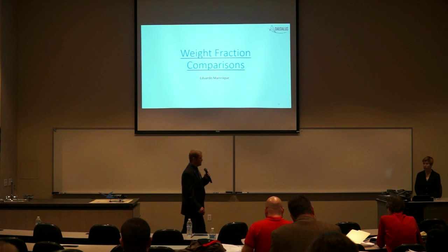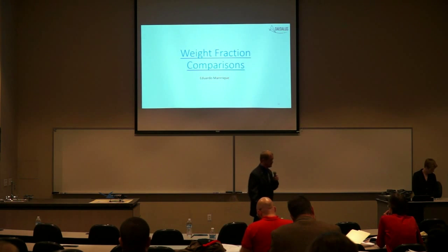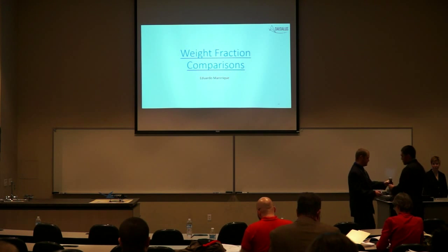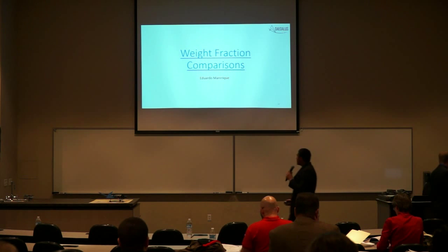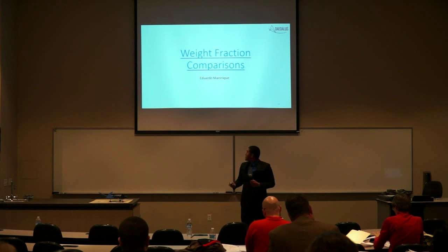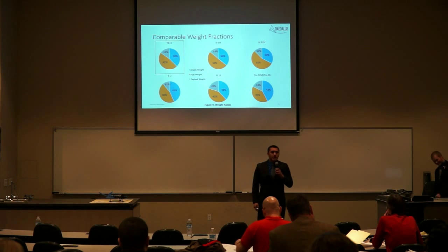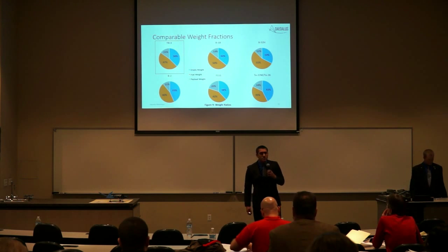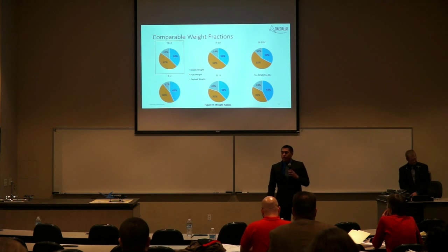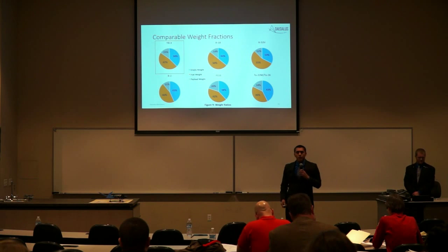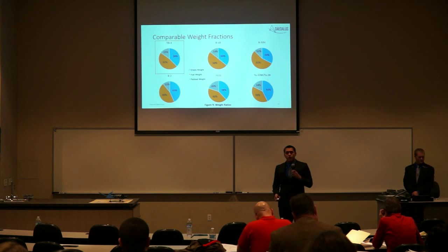I'm now going to hand it off to Eduardo Enrique for a quick comparison. Thank you, Jeremy. With the max gross takeoff weight of 195,000 pounds, 38% of that was allocated for empty weight, 47% for fuel weight, and 15% for payload weight.